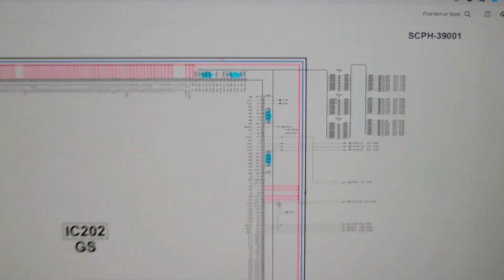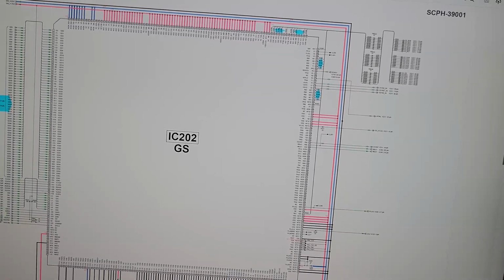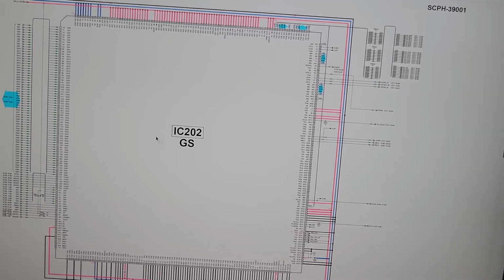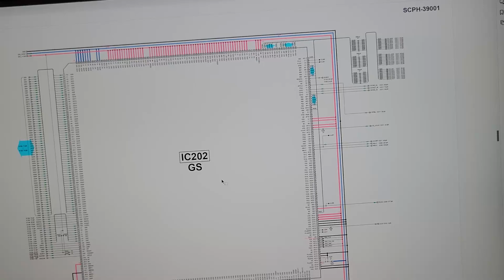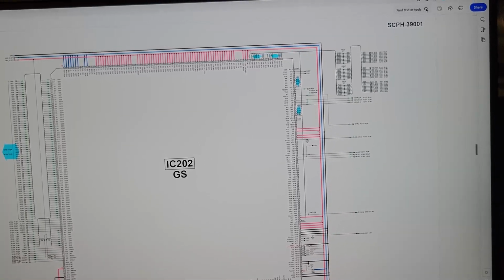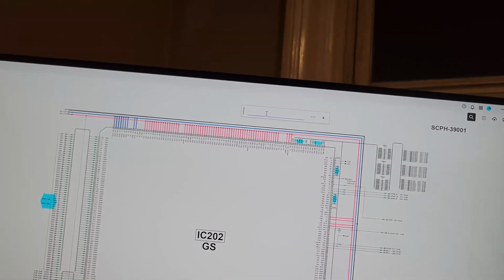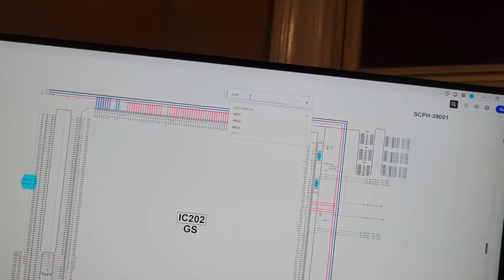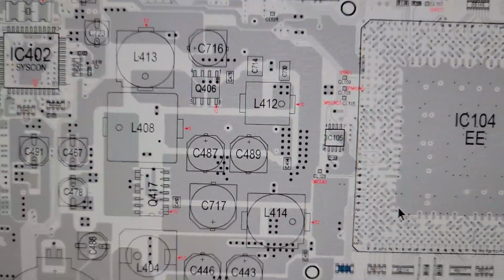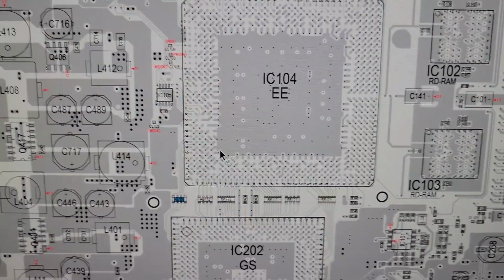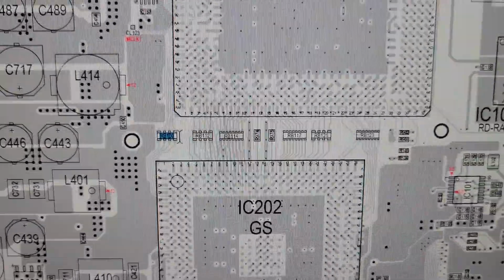Okay, these are resistor ICs. They give you your data bus, they give you your lines, they give you all that stuff. This is what talks to the motion engine and all that, and the 1.8 and all that stuff. But the one I found that was broken that I had was RB109. See this? These are your network resistors on top of the board, folks. There's RB109. This is the one I had a problem with.